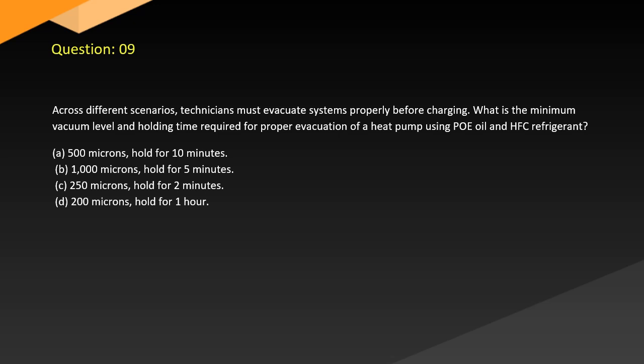Question 9. Across different scenarios, technicians must evacuate systems properly before charging. What is the minimum vacuum level and holding time required for proper evacuation of a heat pump using POE oil and HFC refrigerant? A. 500 microns, hold for 10 minutes. B. 1000 microns, hold for 5 minutes. C. 250 microns, hold for 2 minutes. D. 200 microns, hold for 1 hour.